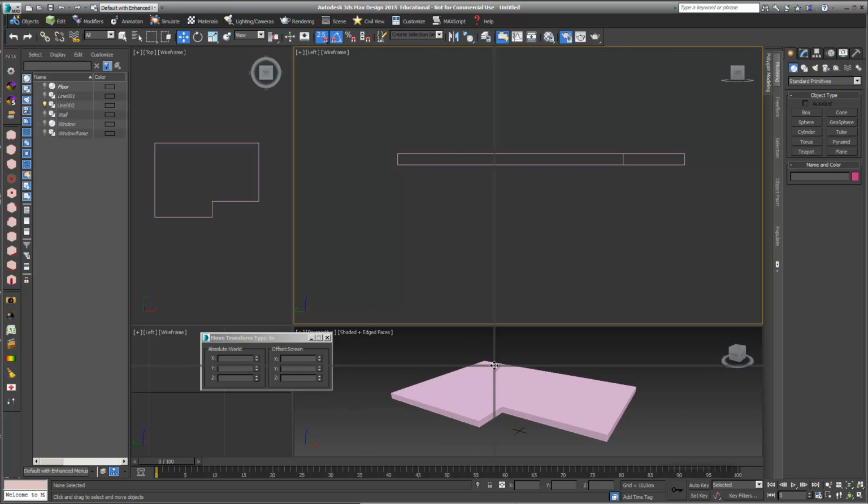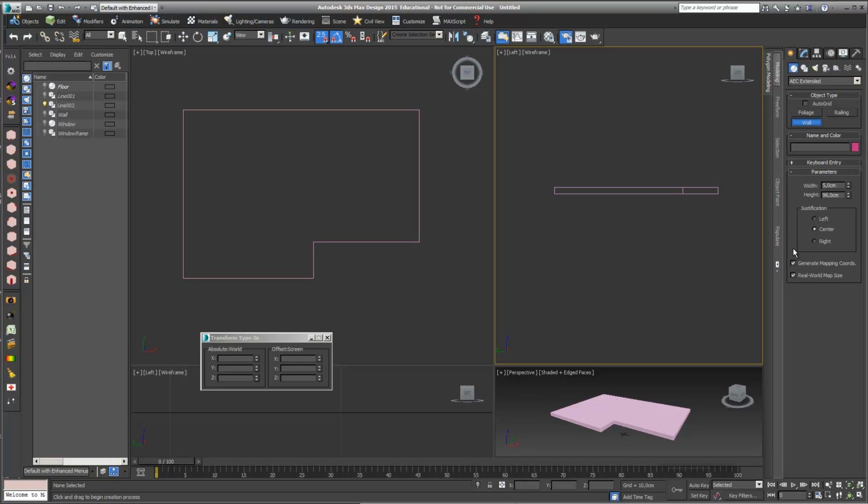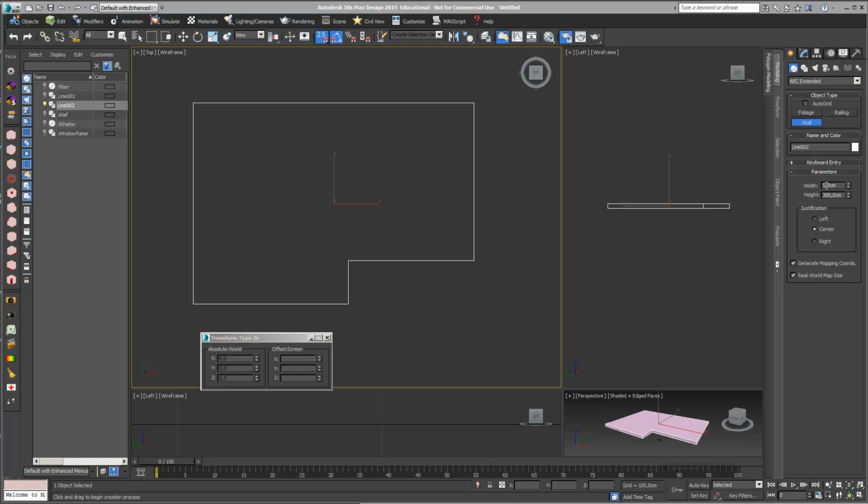And with this we look at the window and the wall tools which are a part of 3D Studio. I just go into AEC Extended, go into Wall, and we can see that here we can already draw walls. I can define the height, and I just say I want to have a height of 3 meters again, and I want to have a width of 30 centimeters. That's the width of my wall.